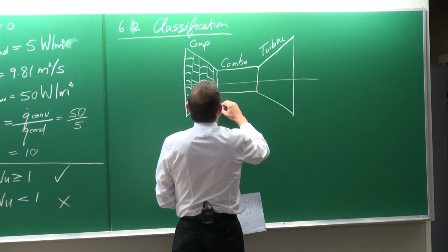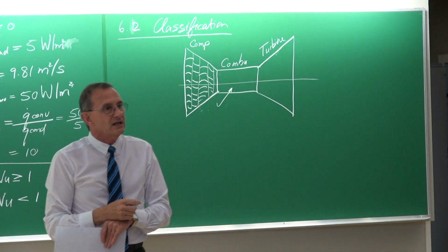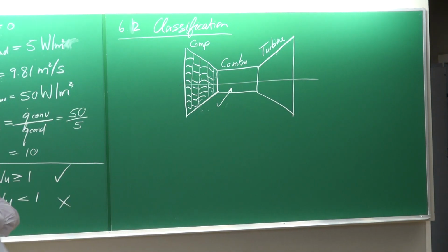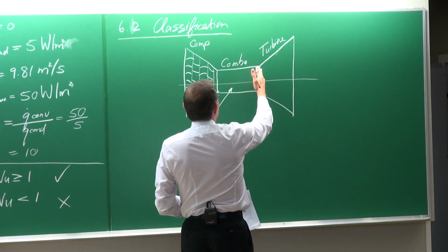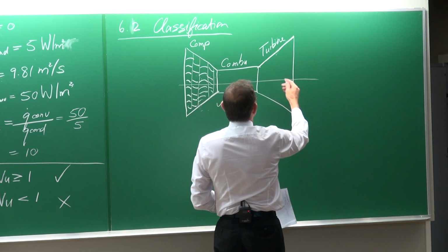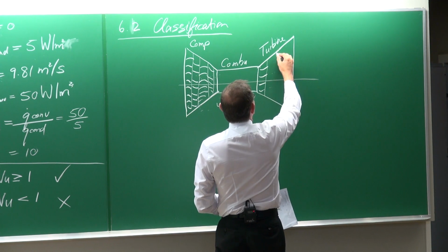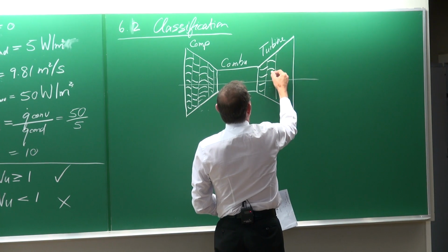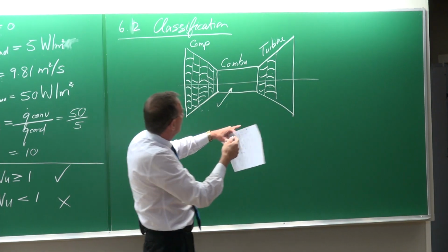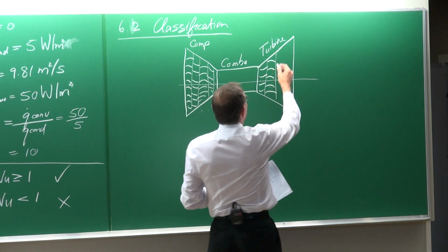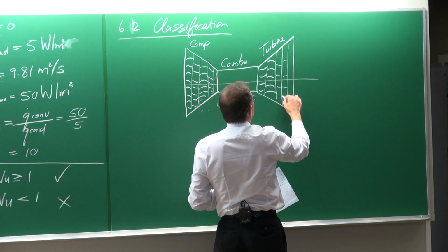Then you will add some fuel to the combustion chamber and a spark, and then you've got an increase in temperature and pressure because of the fuel that is being added. And this gas now is going to then expand through the turbine. And again, the turbine is going to consist of different rows of blades, what we call stationary blades. They do not rotate around. And then after that, there are the turbine blades, and you've got all these rows from one to the other.